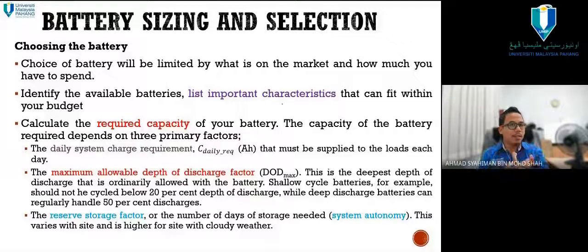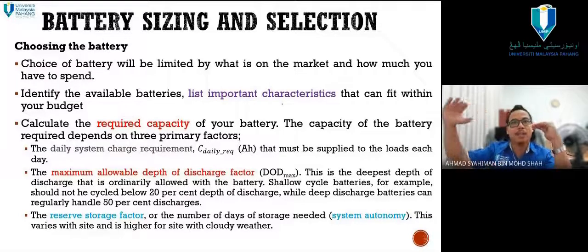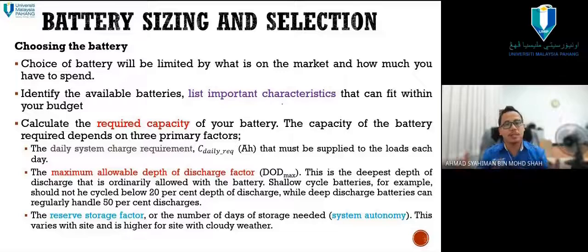Plus, if there is wrong use of the system voltage, like just now, our system voltage is 24 volts but you connect in parallel because you think you need to charge your battery very well. It means we need to amplify the current, so connect in parallel, then you get a higher charging current. That's right. But the problem is the system voltage. If the system voltage is 24 volt and your panel voltage is 16 volt, you cannot charge. Whatever it is, you cannot charge.